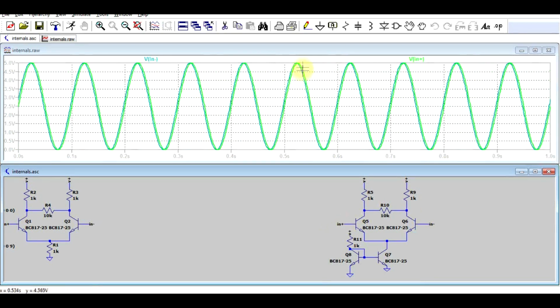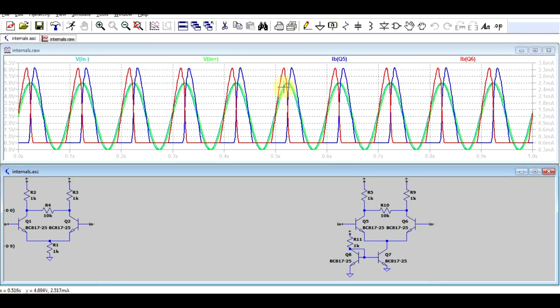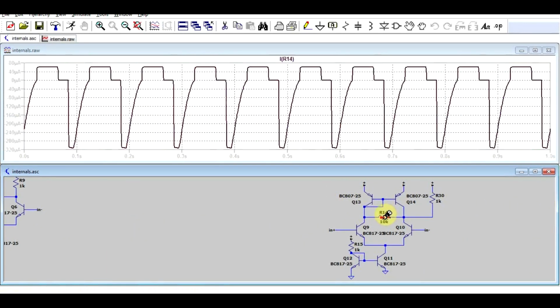When one of the two input voltages is very high, then the current is starting to get drawn through the bases of the inputs. It's no longer coming through the collector. Depending on which voltage was highest, the current will be coming from that side. So our high voltage limitation comes from the upper part of the comparator stage. Now in proper op-amps, this again has been replaced, so you no longer find these resistors, you find a current mirror. What this does is that it gives us a much flatter response.